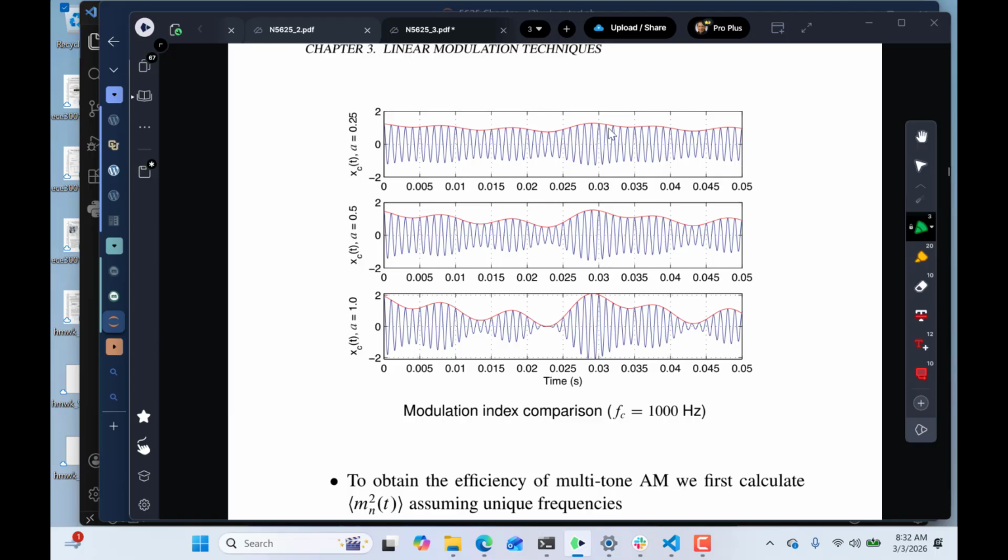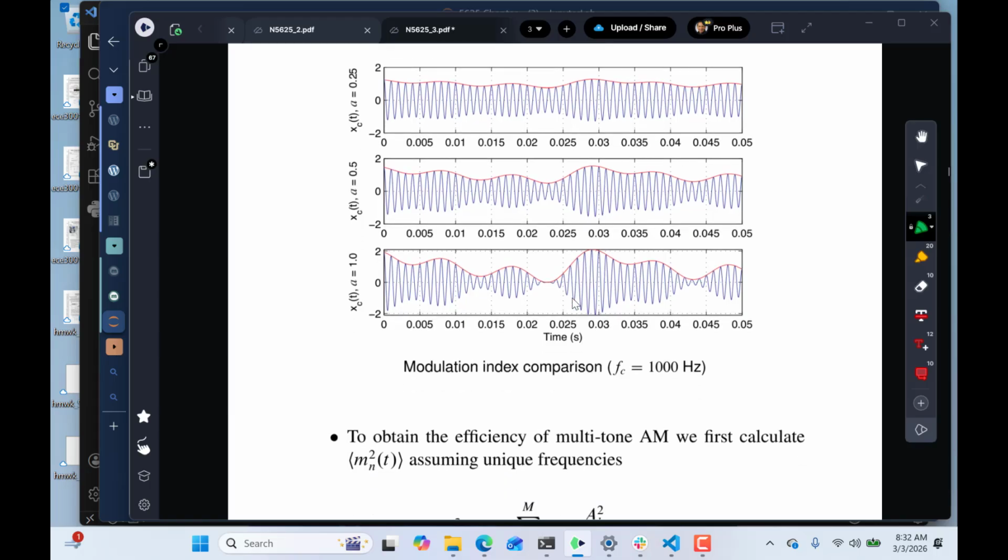Like up here, with a little bit of noise in the background beyond this signal, this would not be as clear as the higher modulation index, but you have to keep it from overloading, so that's what the audio compressor does in a broadcast situation. It keeps it pumped up close to 100% so that it punches through any background interference, and it raises the gain when this person stops talking.